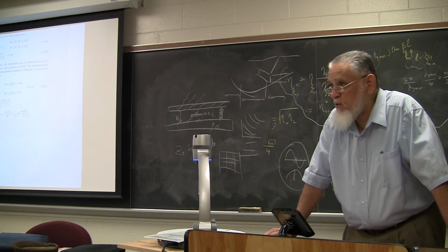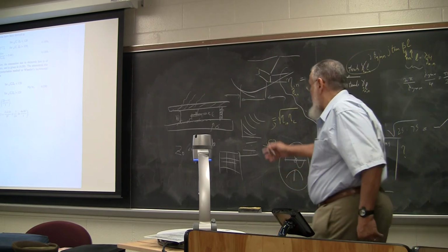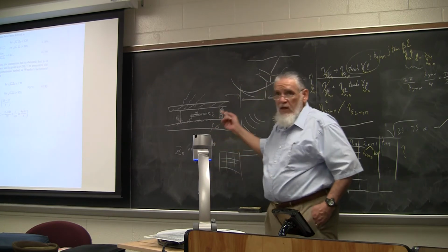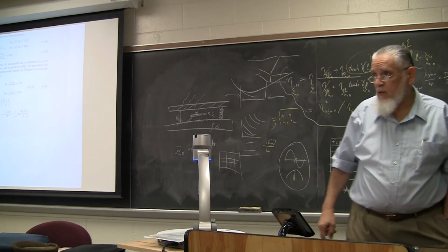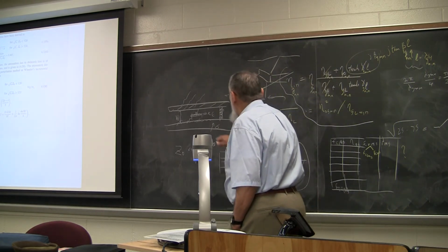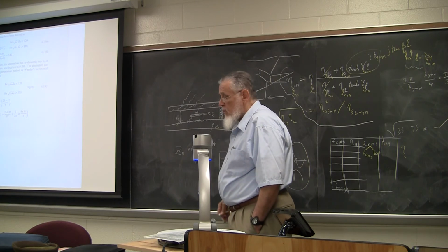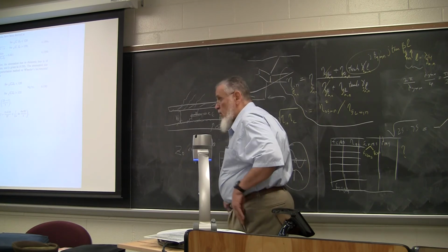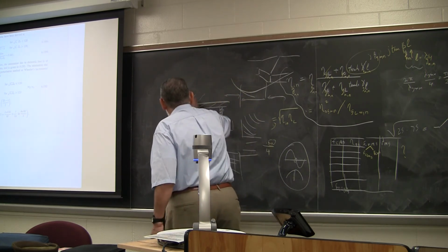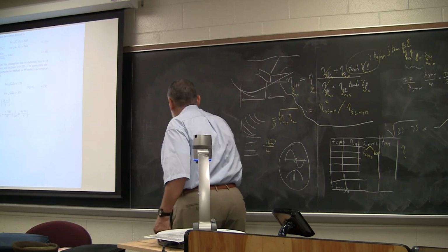They give you the S parameters of the structure. You give a structure like this one here, and whatever you can draw in AutoCAD, you can feed into these packages, with as much detail as possible and as much information about the dielectric and the conductor, and you can get your numbers there. Now, we're not going to do this for every small project that we have. Usually that's done for things that deserve that much research.